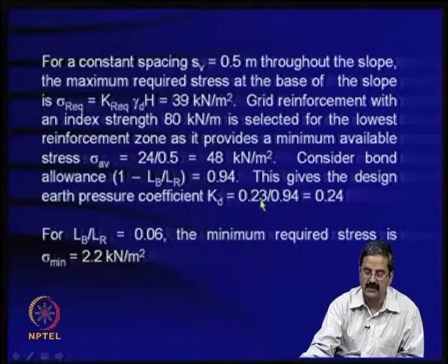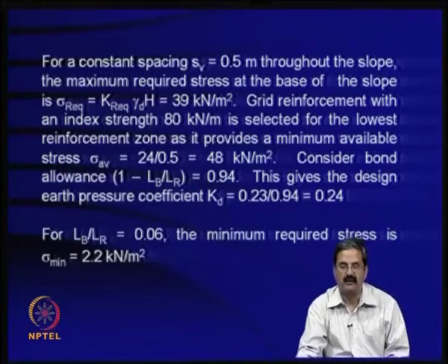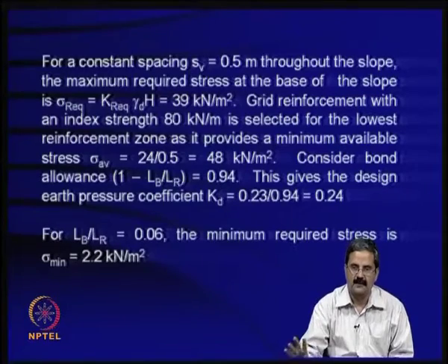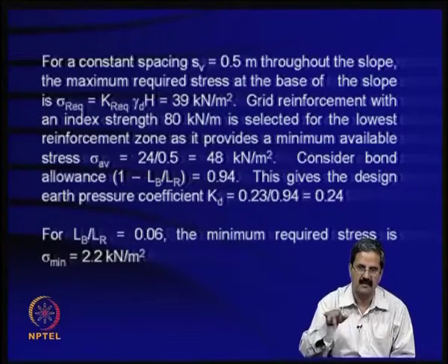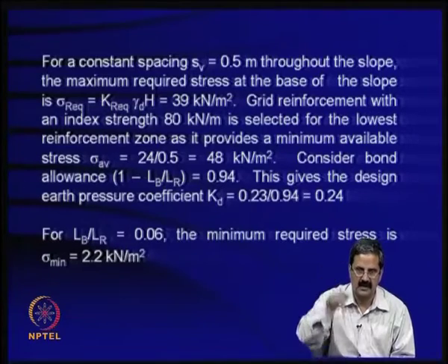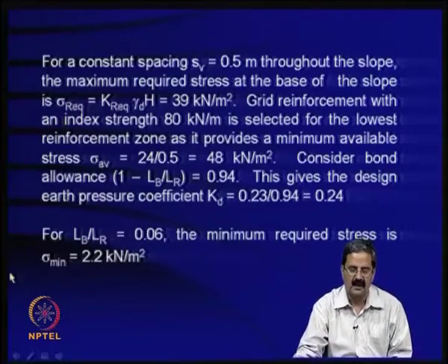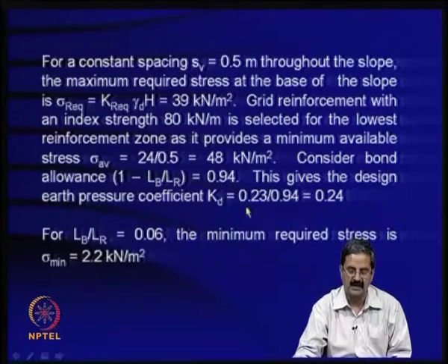as I just mentioned, this reinforcement coefficient, 0.23, which we obtained in the previous step, should be slightly corrected, and this will become 0.24. Essentially, this is because of the orientation effects. Orientation: for tension, the reinforcement should be placed in the direction of tensile strains for maximum benefit, and for the bond it should be placed at 90 degrees to the vertical stress. But in field conditions, there is an intermediate angle, and because of that the K required has to be corrected, it has to be increased actually.